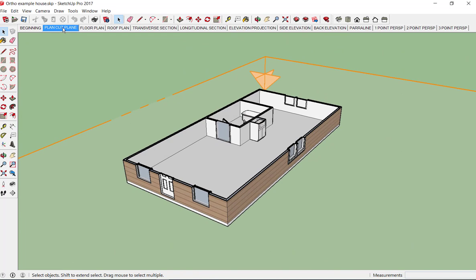So when you cut a floor plan, you're typically cutting somewhere between 4 and 5 feet above the ground, maybe 6 feet. But it's above 3 feet because that's where your lower kitchen cabinet heights are. And it's definitely below 6'8". I don't know if there's a really right answer on exactly where you're cutting your floor plan, but you don't want to cut above 6'8" because then you're cutting above a residential door and you wouldn't see it. So that's your floor plan view. You're cutting perfectly horizontal.